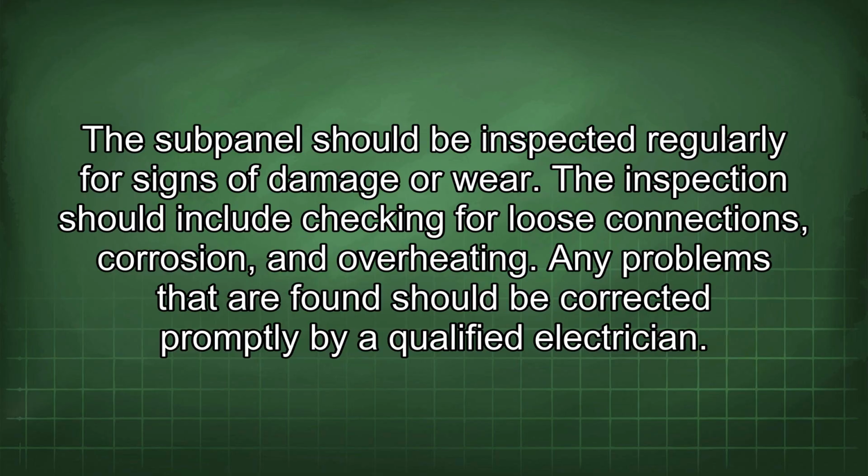The subpanel should be inspected regularly for signs of damage or wear. The inspection should include checking for loose connections, corrosion, and overheating. Any problems that are found should be corrected promptly by a qualified electrician.